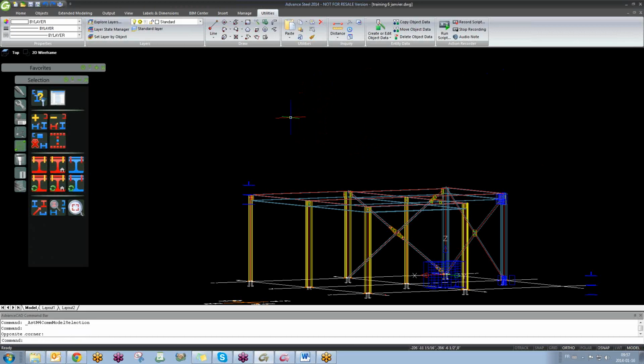Okay, just a different way around from the way we're used to doing it. But it is a way of doing it. I just got to play around with that. Use the user attributes to create the filter. And then I can use that filter to turn it on and off, and then use that color command to go in there and change that floor or columns or diagonal bracing or whatever to whatever colors I want. Yep. I just got to play around with that.